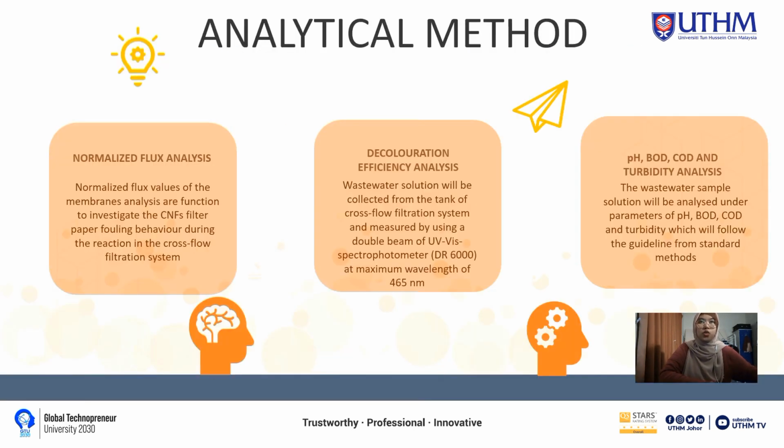There are three analyses which the industrial wastewater sample will undergo after processing via the closed-flow filtration system. The analytical methods involved are the normalized flux analysis, decolorization efficiency, pH, BOD, COD and turbidity. The normalized flux value of the membrane is analyzed to investigate the CNF filter paper fouling behavior during the reaction in the closed-flow filtration system. The value will be determined by plotting a graph of normalized flux against operating time.